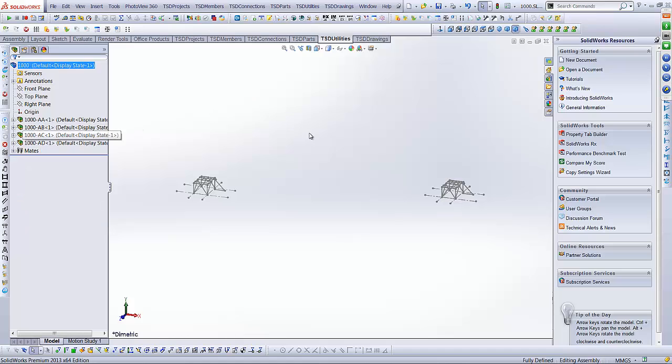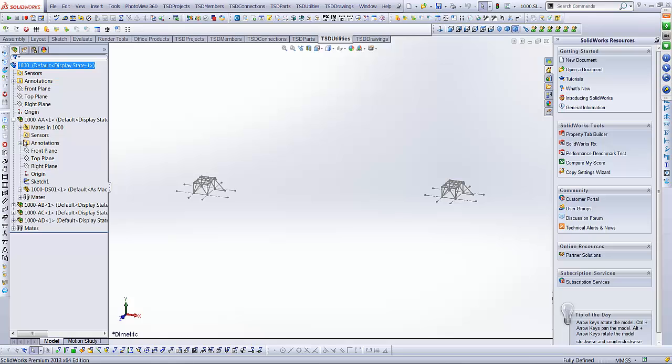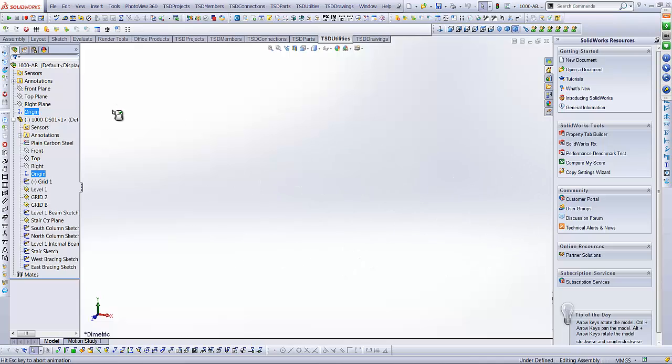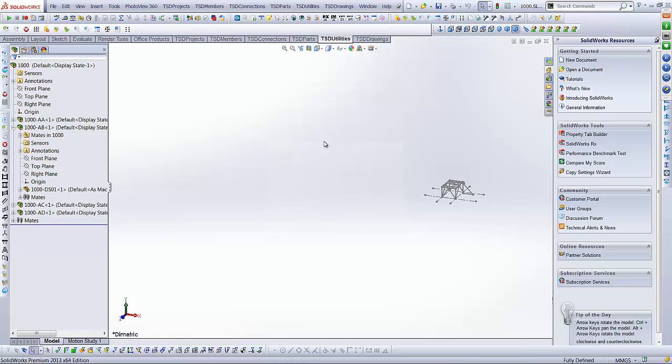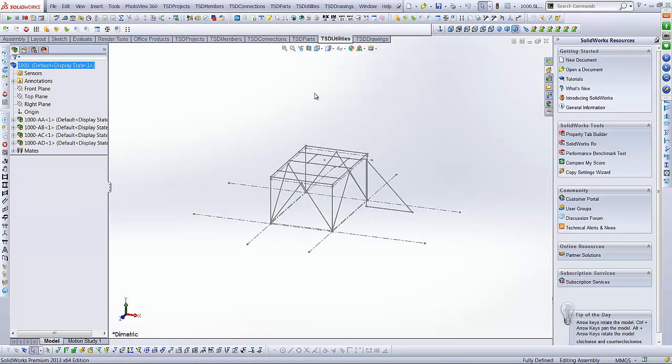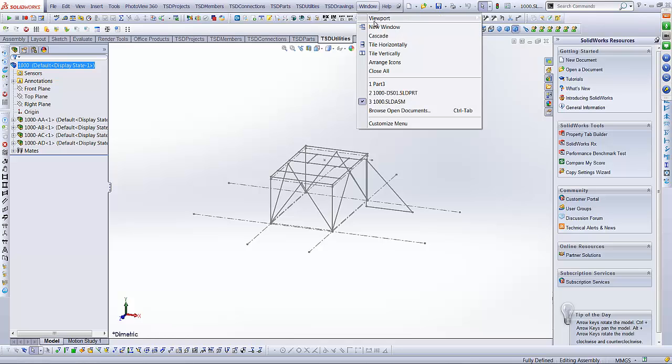Alright, so we've covered those. Now we've also noticed that there's something else that's missing here. That one's fixed. That one there, we didn't float that and align the axes. Origin to origin. That should fix the whole lot now. So now we've got our assembly on top of one another. Also, because the lead designer is going to make changes to the driving sketch, we have to put the driving sketch in here as well.